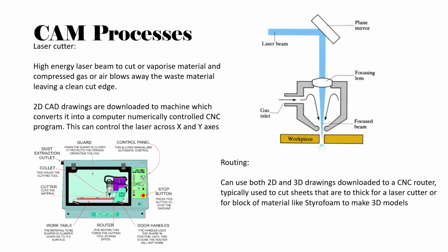So you have CNC mills. You'd have what looks like a drill bit, but it's actually a cutter. And it will cut through material essentially how the laser cutter would, but then you've got to take into consideration the thickness of the cutter and that type of thing. It will let you cut thicker material, so you can do timbers. Obviously, with a laser cutter, unless you've got a really powerful one, you typically do 3 or 6 mil thick material. You might do 9 at a push, but you probably wouldn't. Whereas routing, you probably get to 20 mil, depending on how powerful it is. And you can do things like styrofoam, so you can do prototyping and that type of thing.